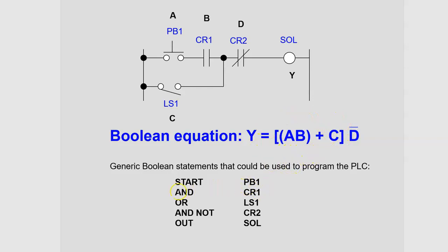Now you might wonder, wait a minute, I don't have any parentheses down here. Well, if you remember from before, we talked about order of precedence, like order of operations. And so I can take these parentheses away if I wanted to, because ANDing has a higher precedence than ORing. So even if the parentheses were not here, the processor would know to AND these first and then take the result of that and OR it with C. And so I don't need any of that over here. And then I OR, and then I AND it again. It says AND, it's NOTed, D is NOTed.